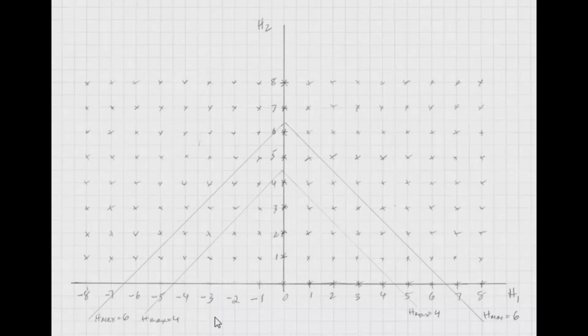I usually just set the harmonic number to 8 harmonics and forget about it. That's probably more than you absolutely need, but on the other hand, it doesn't really cost you much more. Most single tone problems go very quickly, and it isn't going to make any practical difference if you pick 8 harmonics instead of 5 harmonics.